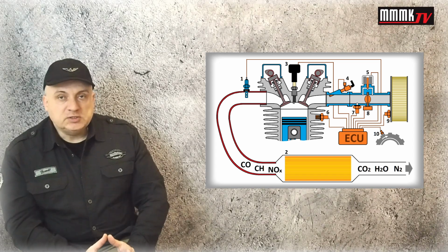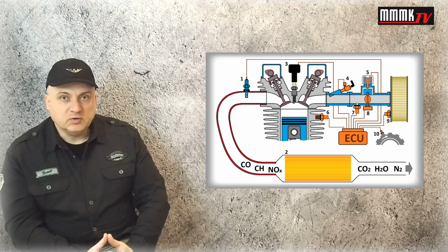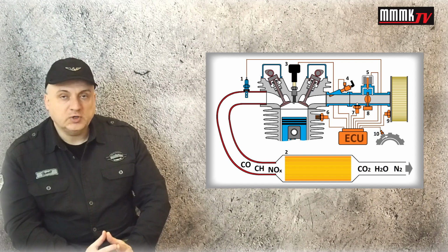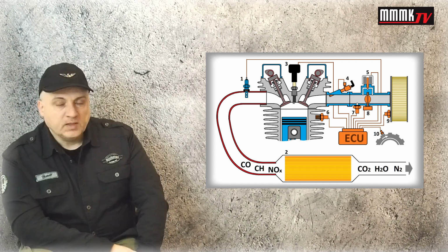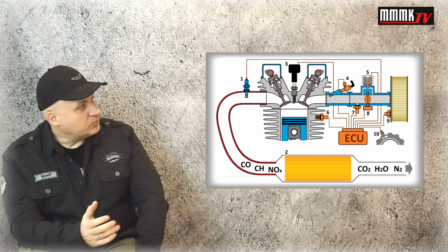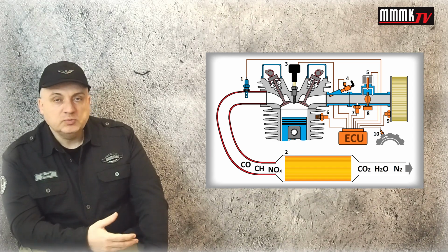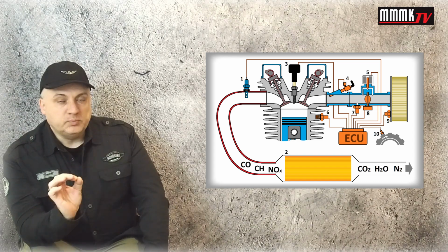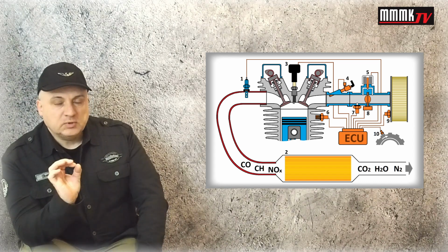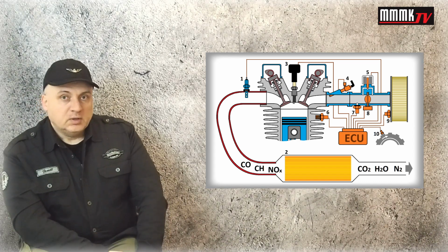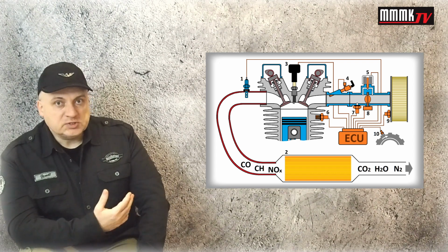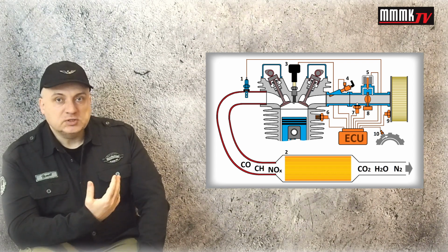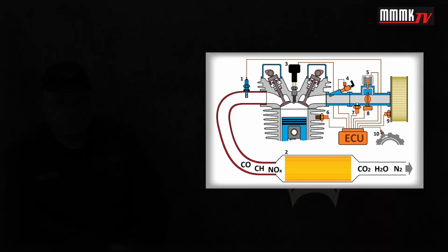And that is the only function of the oxygen sensor in the injection system. I know that some people think that without the oxygen sensor, the ECU wouldn't be able to estimate the injecting dose. This is not true. The lambda sensor doesn't serve that purpose.